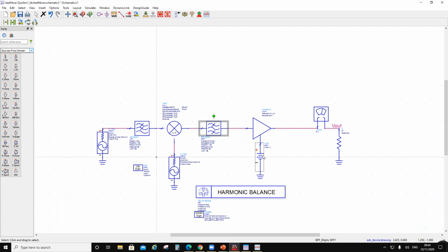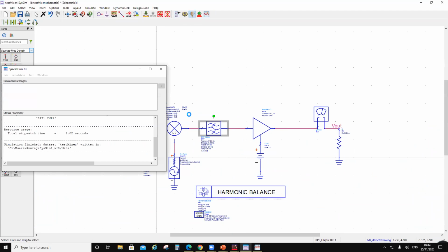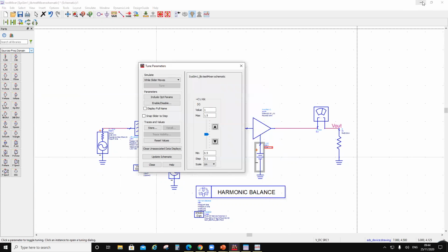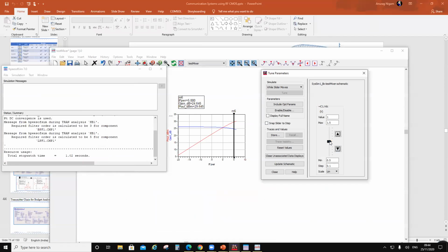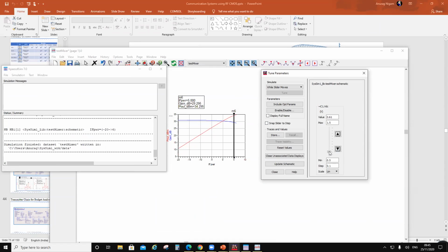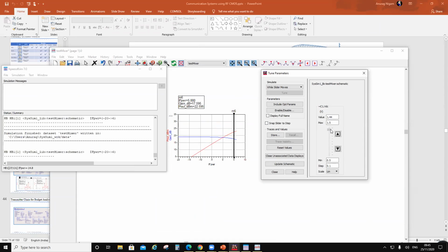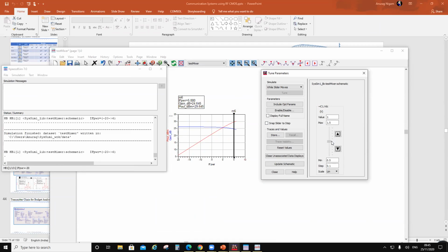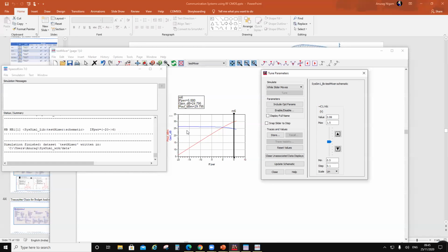Okay, so we have added some voltage gain variation here. If I declare this is called tune, so if I tune this voltage, I would be able to look at what's happening over here, right? If I change this, I can be changing the gain. So that's what the variable gain amplifier is doing, right? So if I put something like 1, so 15 plus 1, so 10.5 dBm plus 15. Okay, so roughly we are in this range. Okay, so that's the story on gain and compression.